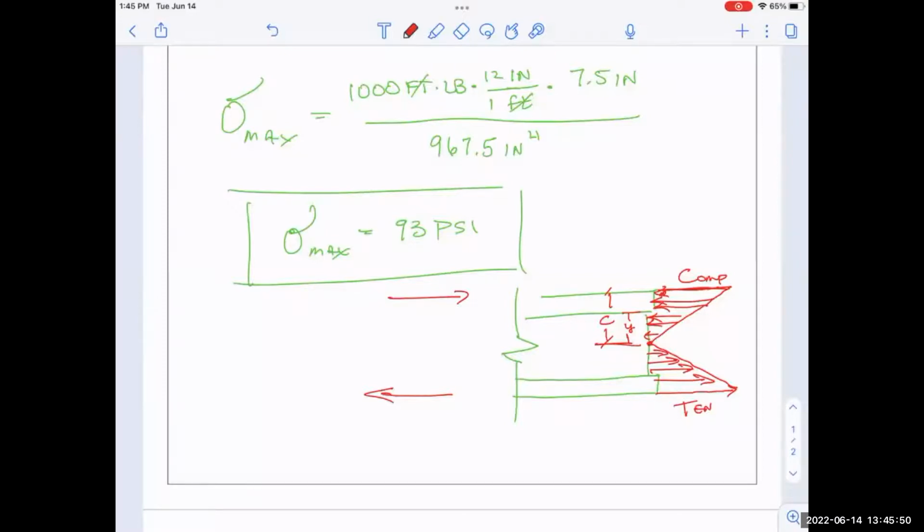Concrete does not like tension. It just pulls apart. It's not glued together very well. Awesome in compression. Put concrete at the top of your beam, if you will, but put a cable at the bottom. Cables are awesome in tension. They like tension. They're terrible in compression, right? Wobbly, they don't do anything. So we're going to get two different answers for this in this case.